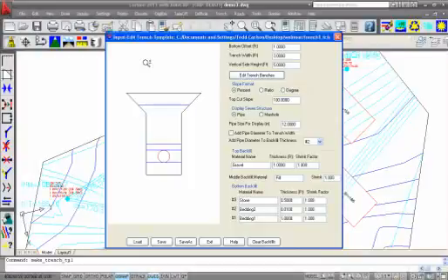Right, yeah. So what this is going to do is give us complete volumes for the stone, bedding, and gravel that we've defined here, a lot more sophisticated than just looking at the plan and estimating by the distance of the pipe, because the depth of the pipe is changing, so some of these materials are going to change depending on the depth and the width of the pipe.